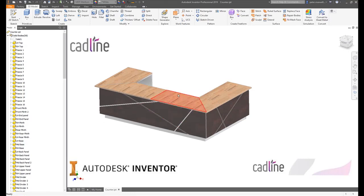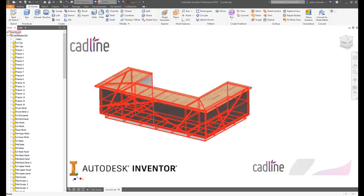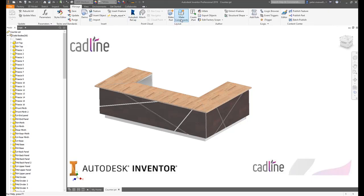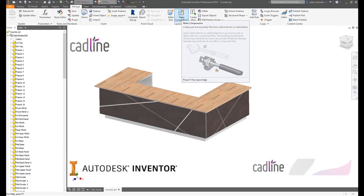Then we need to look at how we can take these solids and turn them into their own individual parts, so we can nest from them or get an accurate bill of materials, because at the moment if I put this in an assembly I'd only have one counter. To do it, it's straightforward: come across the Manage tab, and we're going to go to Make Components.